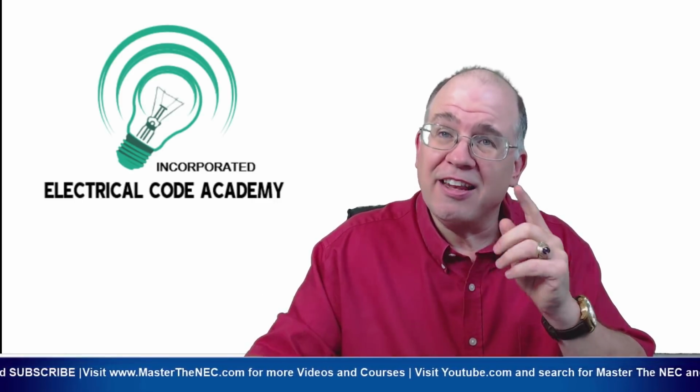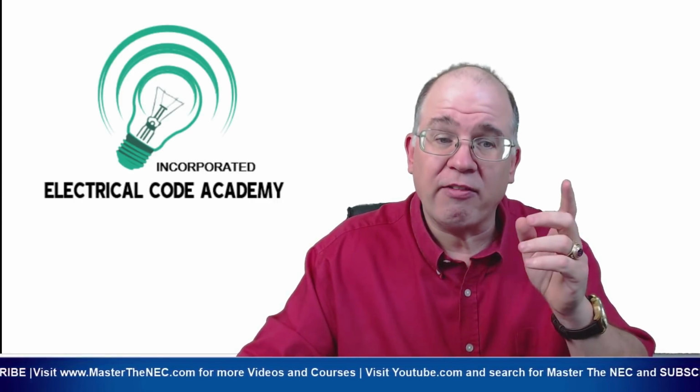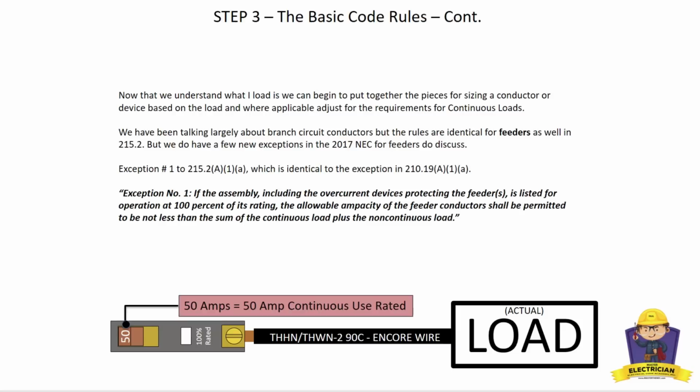So let's look back, and here's what the language says, and you're kind of already familiar with this because we've discussed it. It says, if the assembly, including the overcurrent device protecting the feeder, is listed for operation at 100% of its rating, you saw that earlier for the branch circuit application, the allowable ampacity of the feeder conductor shall be permitted to be not less than the sum of the continuous load plus the non-continuous load.